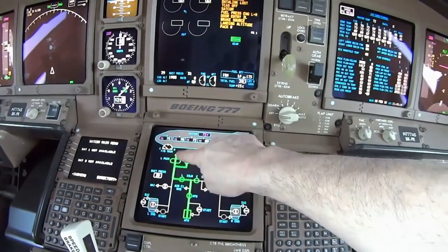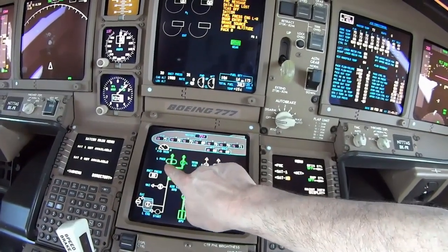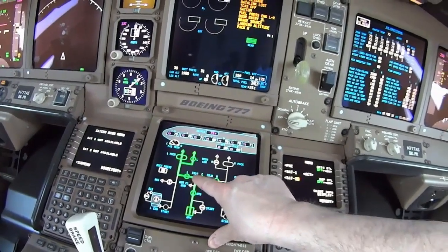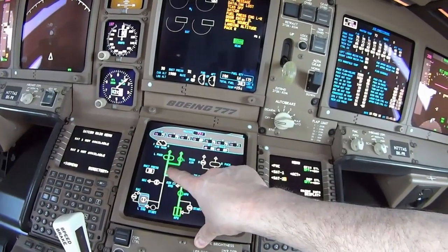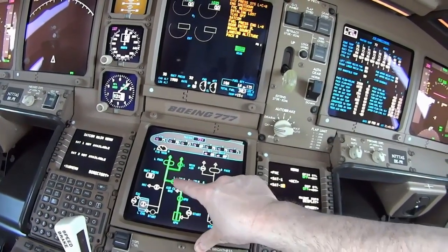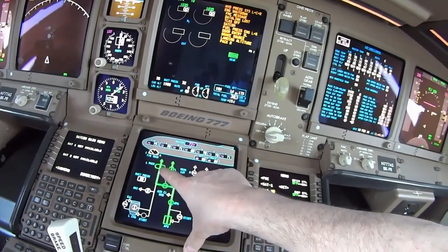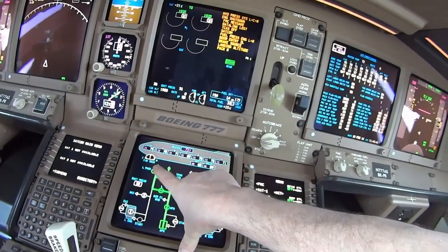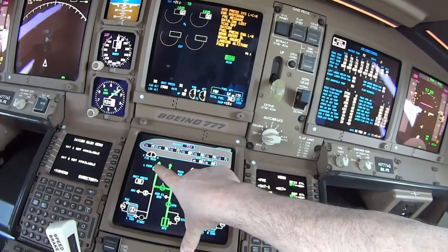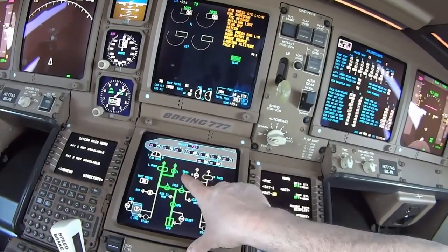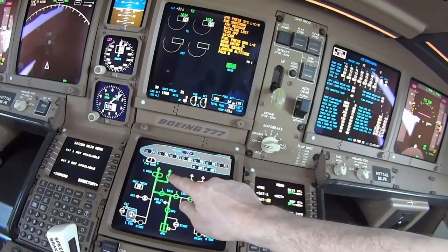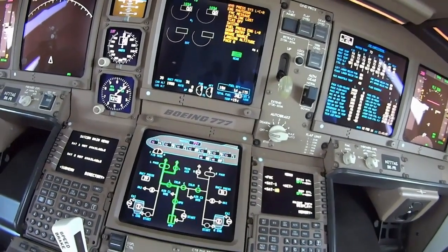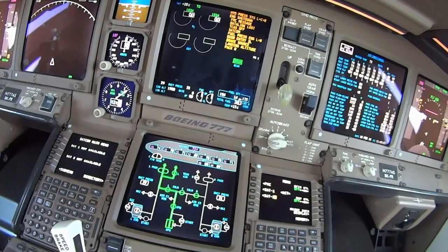All right, so that's our air that goes into the pack system. Then we have this hot air coming out of here. This is several hundred degrees, maybe 400 degrees or more, 450 degrees. Very, very hot air coming off of the jet, off of the APU engine. And so hot air goes in there and hot air goes this way. And this air is going to get cooled down and come out at about 32 degrees Fahrenheit. And the air that goes this direction is the trim air. That's going to stay hot, and once this air comes out and goes into the duct, this air will be mixed into it to control the temperature, and that's how that works.